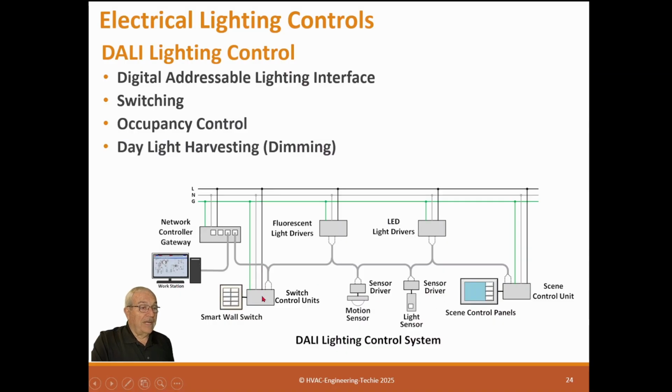And this also allows these lightings to be integrated up the ladder to a BAS system or any other control system, a SCADA control system, because it's just a digital control system. And you can integrate with it so you can see the lighting or control the lighting by more than one source. So that's why they have DALI systems.